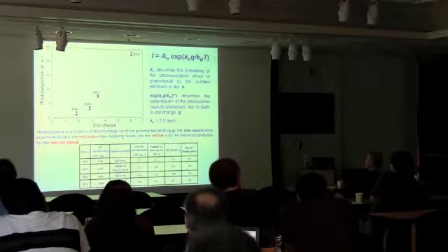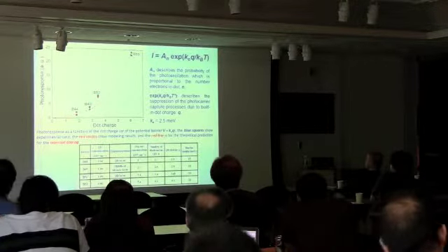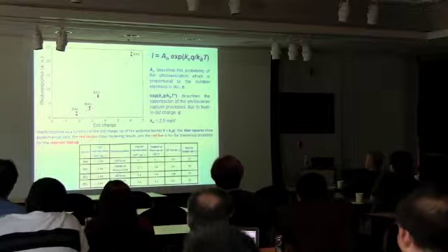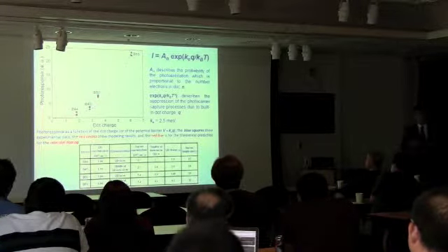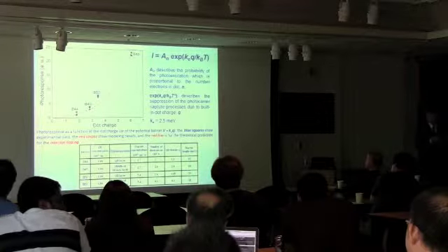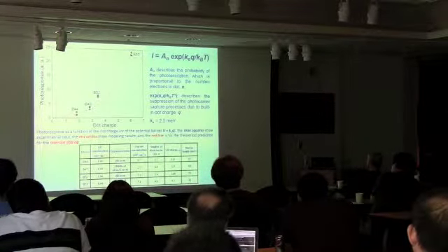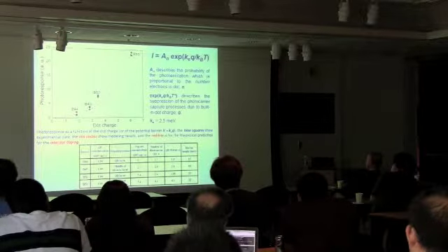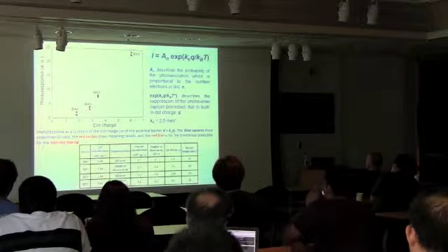That is why, what we have is the same doping with approximately the same number of electrons in the dots, but in the first case, when we dope inside of the layer when you grow dots, some impurity goes into the dots, and so the charge of the dots is smaller than the dopants outside.